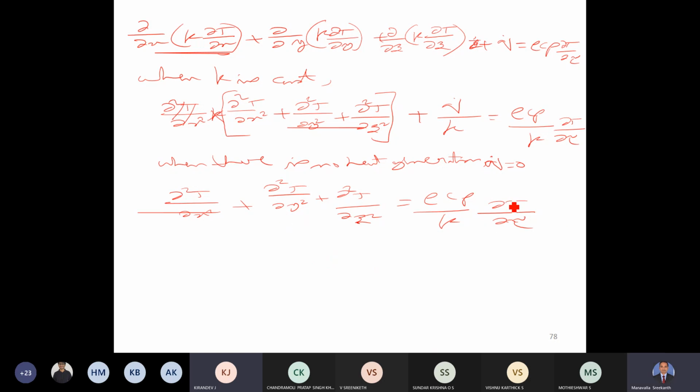So from this, to answer the question asked whether the temperature changes with respect to time or not, we will have to evaluate this particular term. To evaluate it, we should know the values of ∂²T/∂x², ∂²T/∂y², and ∂²T/∂z², and also the values of rho, cp, and k. In the problem we are not given the values of rho, cp, and k, but we will see.